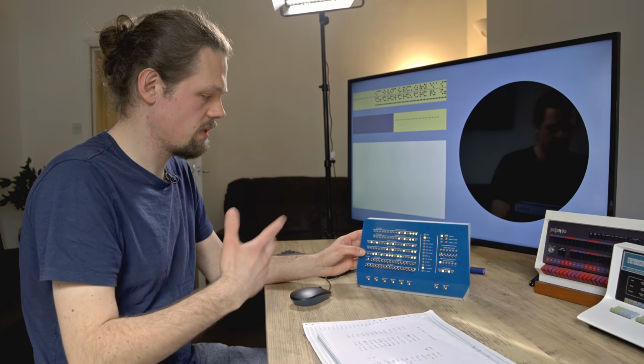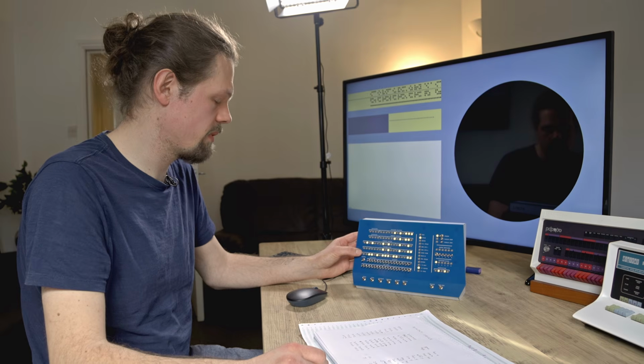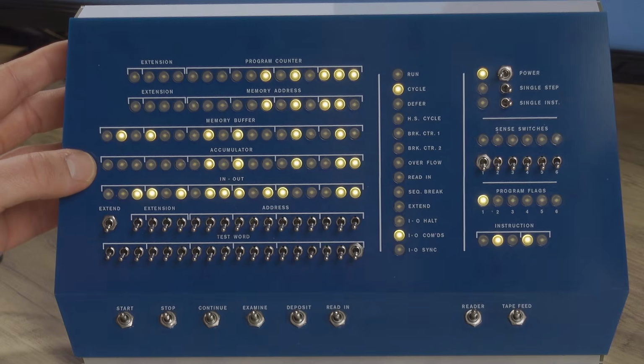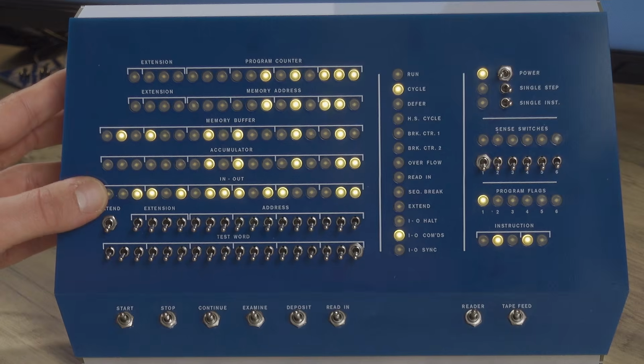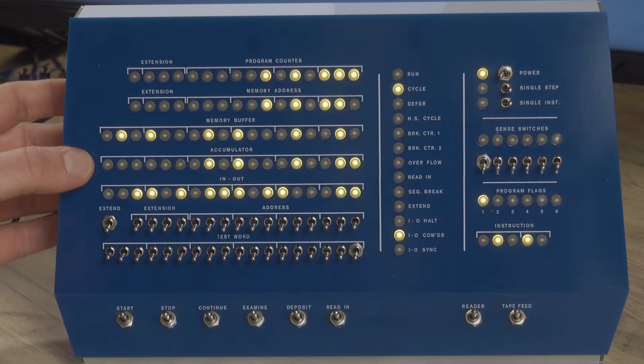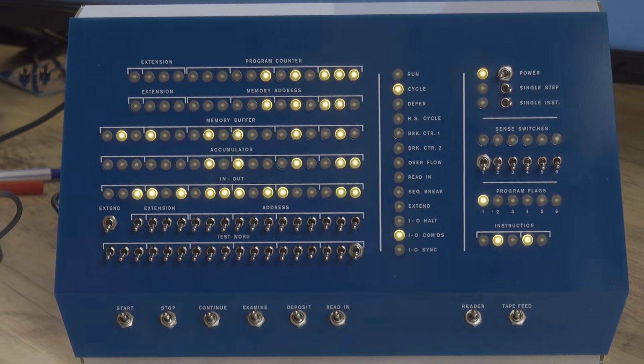And the accumulator and in-out register are what the programmer uses. And as you can tell from the name, in-out is also connected to the peripheral equipment I/O stuff. So the accumulator is the arithmetic register that you control with your program, more or less. And I/O was also used as an auxiliary register. Also, when we display a point, it will be X and Y coordinates. One register is X, one is Y.